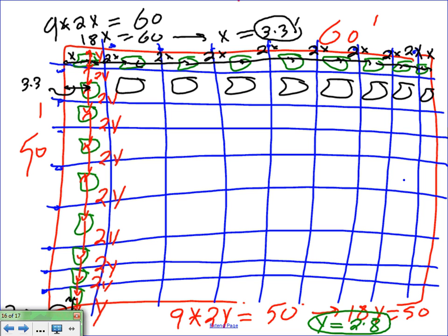We talked about this today, guys. In a clothes closet, what type of fixtures is allowed to be installed? And also the clearances. I summarized it to you today. I said everything is 6 inches except surface mounted LED and incandescent. They're 12 inches. All other types are 6 inches.